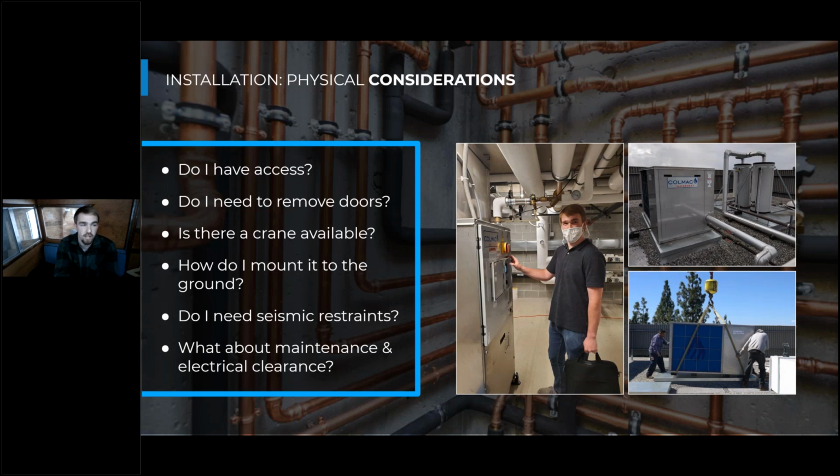Or in a retrofit case, do you need to actually remove components of the heat pump, or remove the door frame or the doors themselves, to be able to fit the equipment into the room, into the physical space? And if it's on a roof, have we scheduled a crane to overlap with the actual delivery date and installation date of these heat pumps?